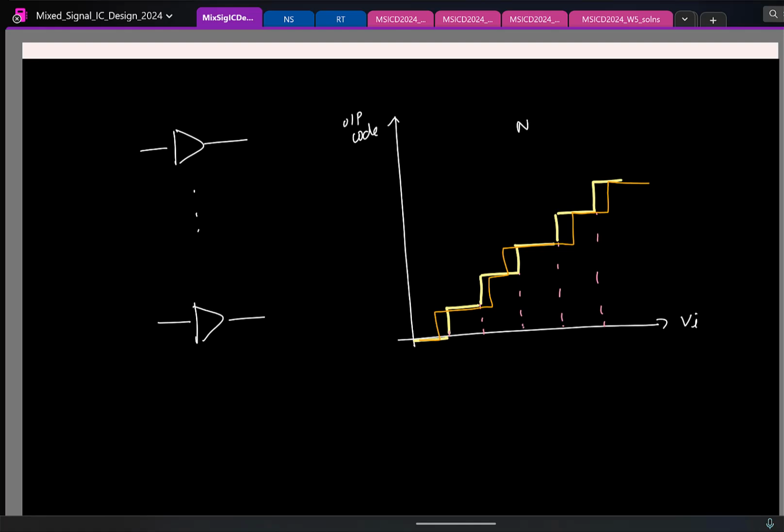So this straight away introduces non-linearity. This is going to be a real problem, so we have to see what to do. Again, the thing to notice, if all the comparators had the same offset, this is not a problem. Because it's random, we have this issue. So let's see what we can do.